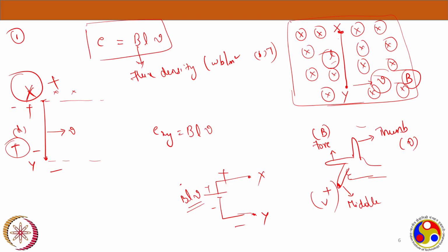Now I hope you understood this concept of Fleming's right hand rule. The right hand rule is correct, as you have said, but you have to observe the directions: which finger denotes which quantity, and the placement of the hand is also tricky. You should not get confused. The thumb denotes the velocity, the forefinger the magnetic field, and the tip of the middle finger should show the positive polarity of the induced voltage.